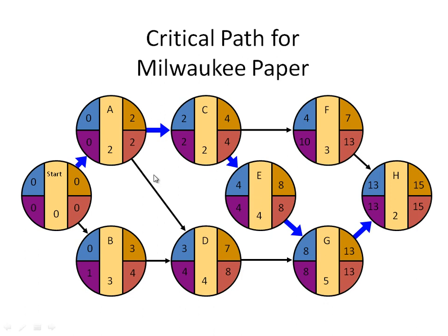But again, we have a limitation, and we have to calculate the slack time for each of these activities and make sure that we are not exceeding the limit to affect the schedule. So we have a certain amount of time that I can utilize, but not exceed that limit.